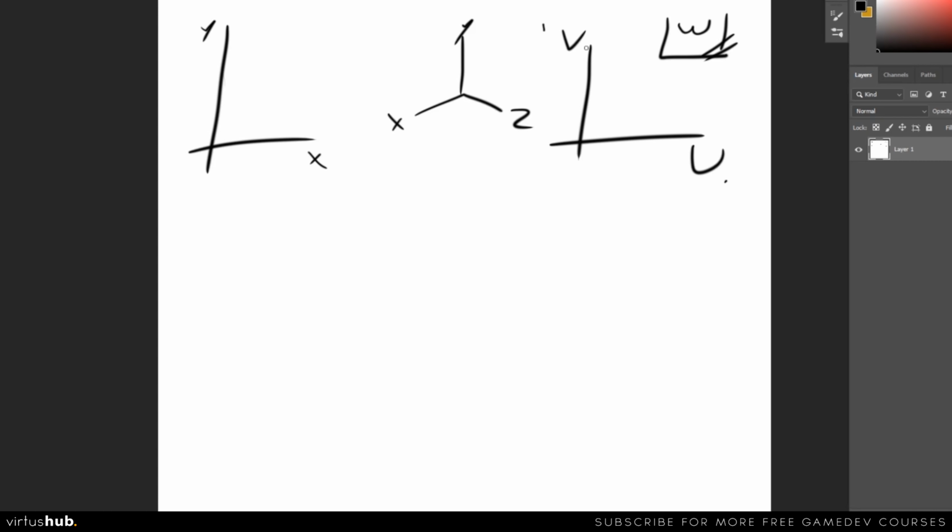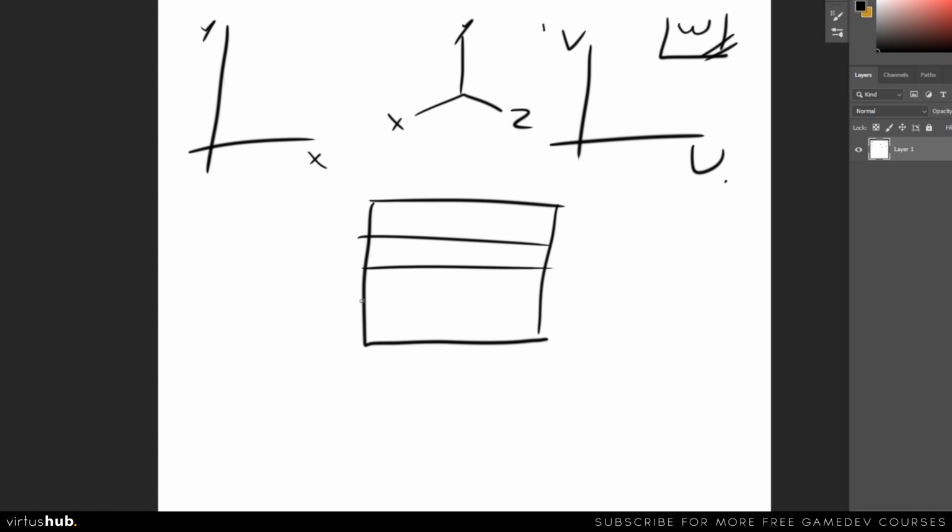The second concept that I want you guys to know is that whenever we're dealing with textures, or at least the basics of texturing, we only have one particular space. So when we get into the 3D program, you're going to see that we have a defined space, which I will be referring to as the 0 to 1 space, because it's one full tile that goes from 0 to 1 on the U and from 0 to 1 on the V. And this is where we're going to place our textures. There's something else called UDIM tiling, which is a little bit more advanced. We're not going to talk about that in this tutorial, but just know that that exists.